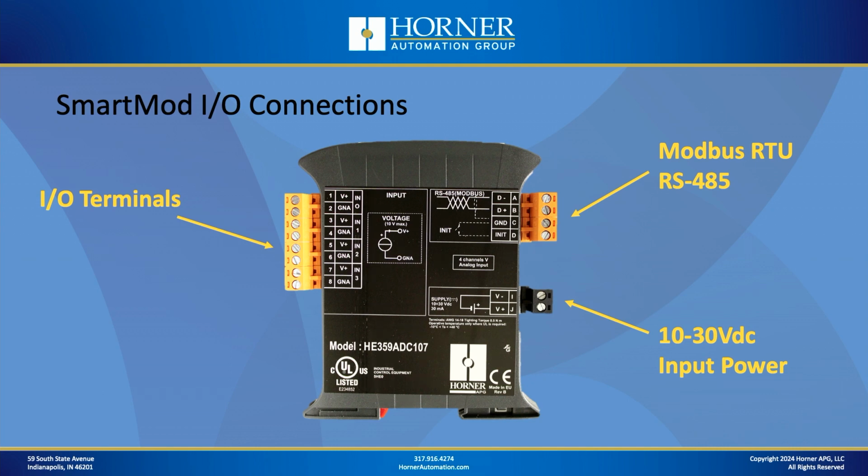At the top right there, you have your Modbus connections, which is typically 3 wires. You've got a twisted pair, data plus and data minus, and then a common terminal, which is used for a ground reference. All right, so typically you're going to have 2 twisted pairs with 1 pair for data and 1 other conductor of the second pair used for common.